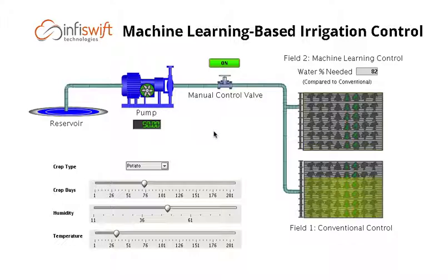We have a simulated evaporation happening, and so you can see that when the field reaches the top with the green color, that's simulating reaching the end of the irrigation cycle, both in the conventional side, which is just time-based, where we're not paying attention to plant-specific water needs, or in the machine learning controlled field, where it's reaching the point where the algorithm says we've applied enough water that the plant is going to get everything that it needs to absorb to be healthy.